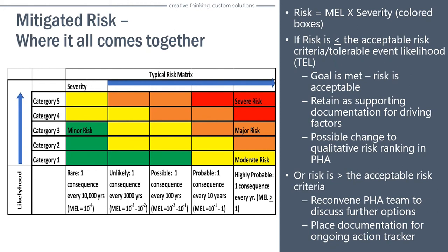What you find is that you may have to switch or modify your process from being very manually intensive to adding more automation, because automation does increase the independence of your IPLs and does reduce your risk. And so typically, if you find that you have an older process where you're relying a lot on manual intervention, you may find that you are not meeting your risk criteria and you have to add some automation in order to make it more risk tolerable.